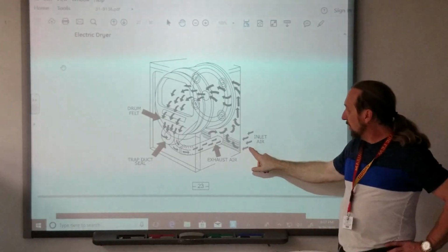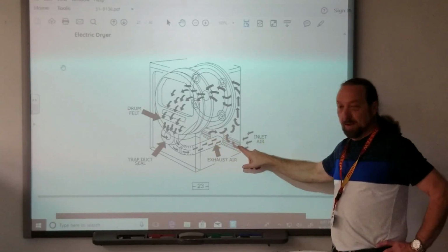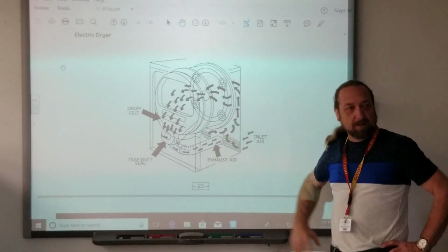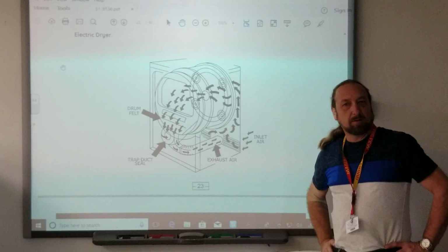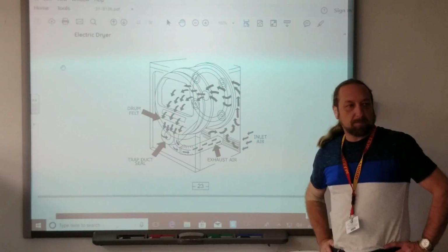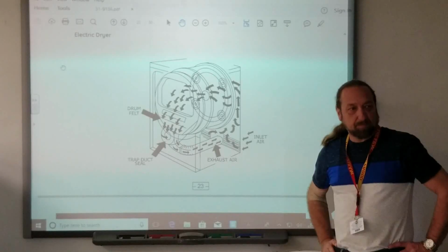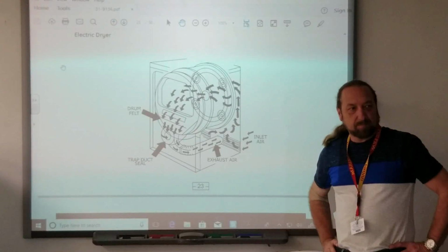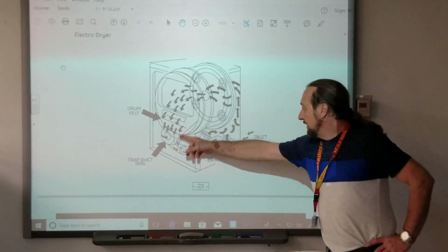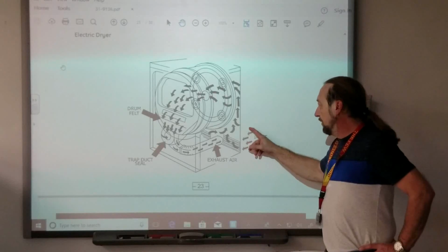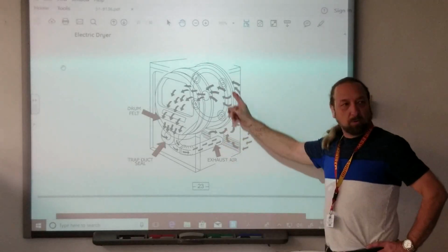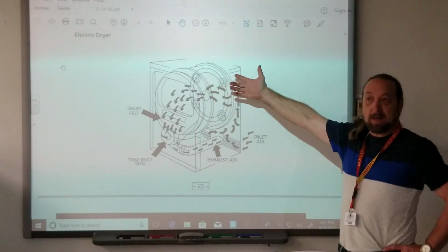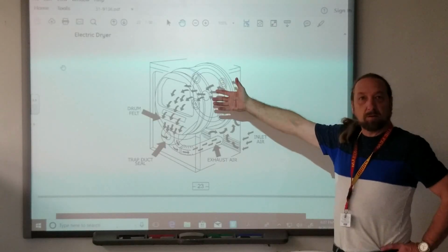Yeah, but if you look, the inlet air is coming in through vents on either side, right back in where the hot air is coming out. Because the blower that we have is not going to recirculate the hot air. No, it's going to circulate the hot air out, but is it good for that same hot air to go right back in the dryer again because it's hot? It would make it a closed system.